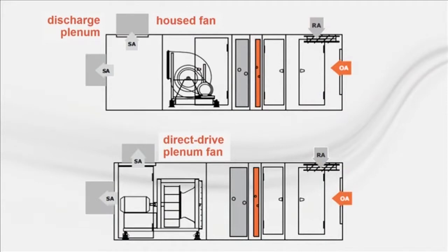So, if the air handling unit has a draw-through fan that discharges directly into a sufficiently long, straight section of duct that's about the same size as the fan outlet, a housed airfoil fan will typically require less power than a plenum fan, but a plenum fan will likely have lower discharge sound levels. Let's look at another example.